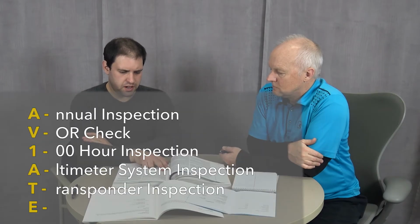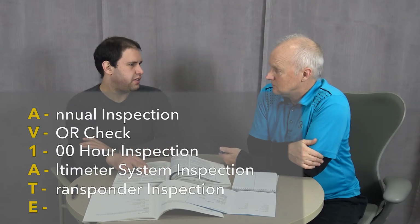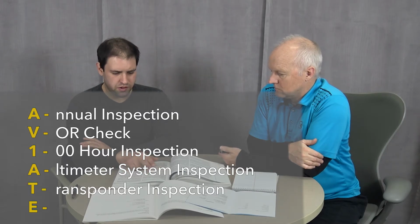Next one is a transponder inspection. Since the transponder runs off the pitot-static system, same as the altimeter does, those are usually done together at the same time, and they're both 24 months. Once again, the Chief doesn't have a transponder, so we don't have to worry about that.